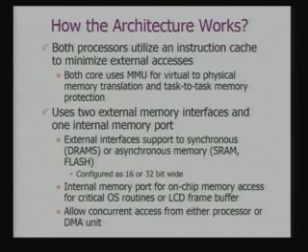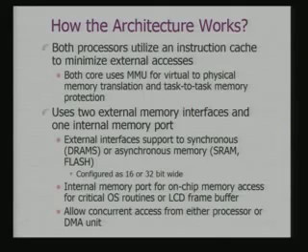In fact, if it is targeted for mobile applications, there would be a requirement of a display panel, and the data to be displayed on the panel is stored in a frame buffer, which is again a memory area where you have a mapping from each pixel on the display to a memory location in the frame buffer. That would be very frequently accessed, because there you actually have updates to be displayed to the user. So, that also forms part of your internal memory.